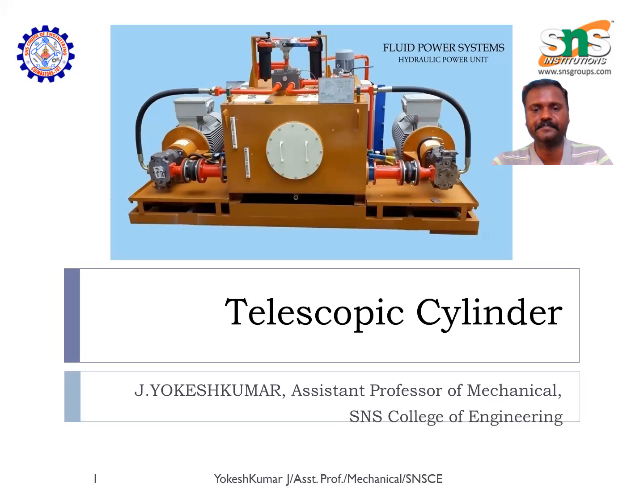So this telescopic cylinder can be used whenever we have space restrictions. For example, for extension we need a very long stroke, but for retraction we have space restrictions. We need to accommodate it in very little space. Telescopic cylinders can be used.